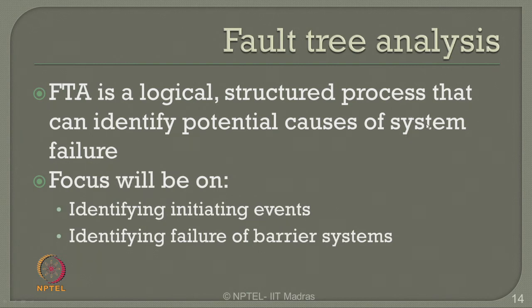It can also focus on a subsystem depending upon the requirement or intricacy of the FTA. The FTA will essentially focus on identifying the initiating events and then subsequently identifying the failure of any barrier systems available in place in a given plant.